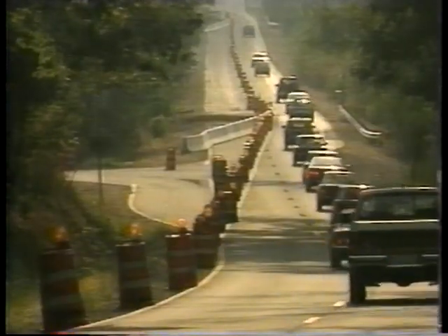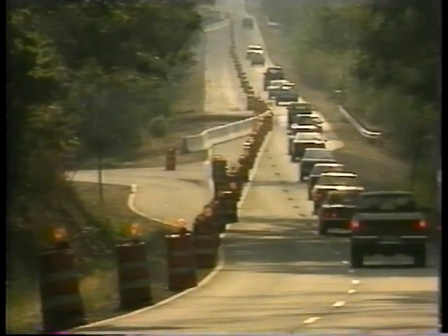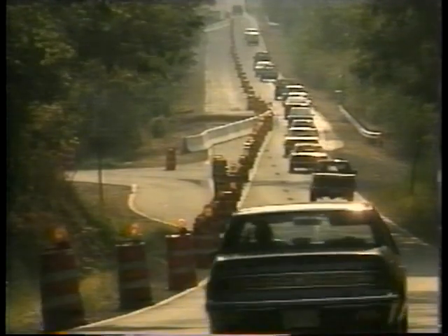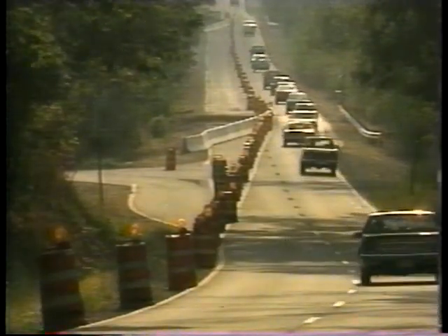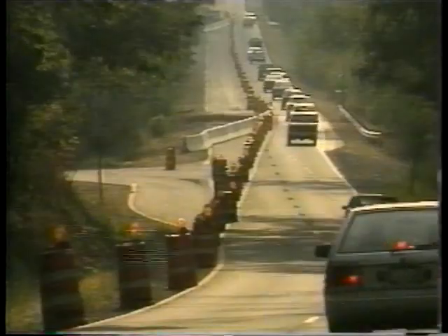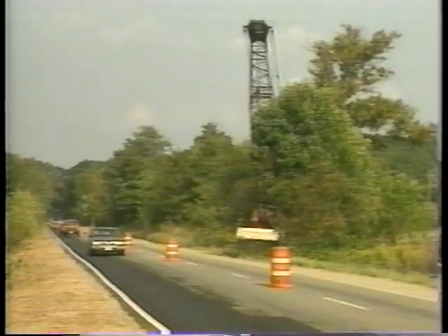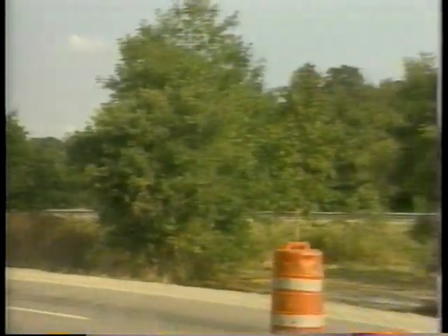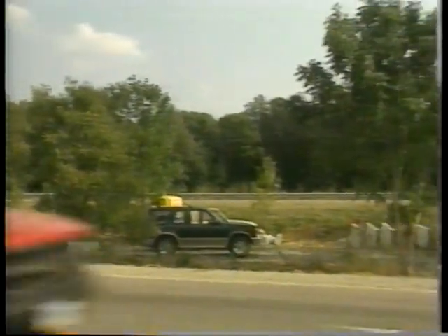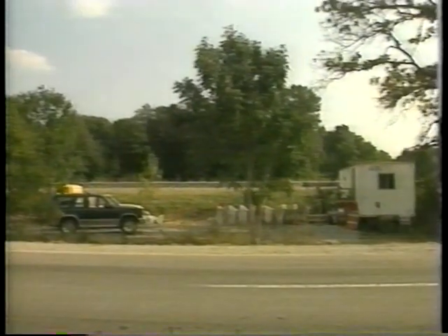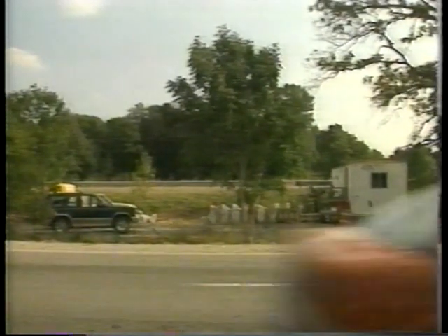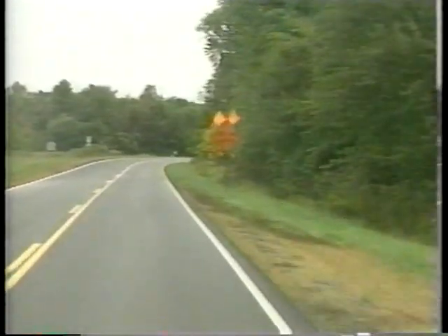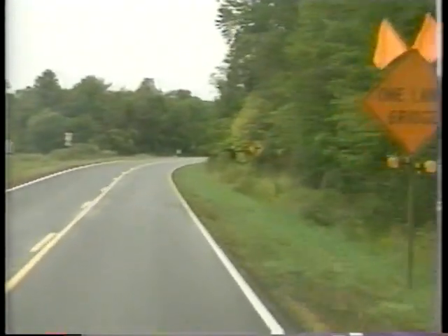Also, avoid abrupt changes in roadway geometrics, such as dropped lanes or roadway transitions, that force drivers to make rapid maneuvers. Don't forget to provide for safe operation and storage of work vehicles. And remember, drivers will reduce their speeds only when they think they have seen a real need to do so, which relates to the third principle.